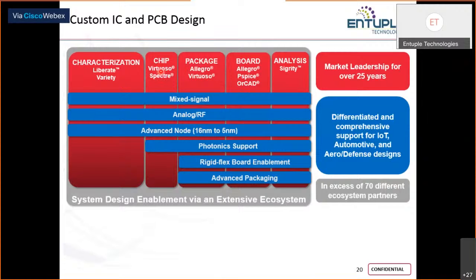Okay, and then for the simulation aspects, that is the types of analysis, small signal AC and DC analysis, transient, and noise analysis, we have a tool called Spectre. Okay, Spectre is a simulation engine which will help you in running through the circuit simulation. Okay, and then we'll be talking about the layout, right? So Virtuoso layout editor helps you in designing the layout.